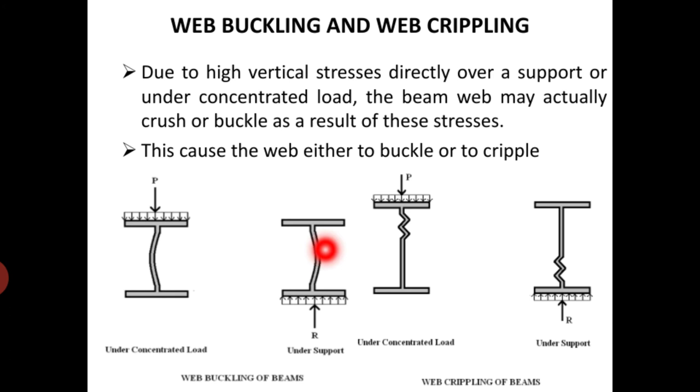And some of the experimental results have indicated that for rolled steel sections, the researchers said the tests indicate that for rolled steel beams the initial failure is by web crippling, rather than by web buckling. Generally the first failure takes place by crippling, then the web of the beam buckles. That has been indicated in some of the experimental tests.